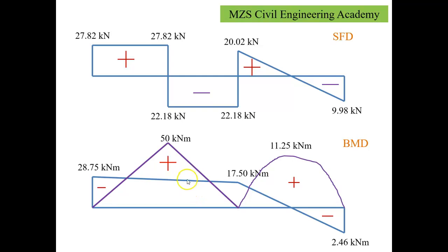If I overlap these two, I will get the area which is under common integration. The area under common integration, if I consider, will be said to be the net bending moment diagram for the given case. That's all. We have solved the shear force, we have drawn the shear force diagram, we have drawn the BMD diagram, and the total analysis of the numerical has been completed.